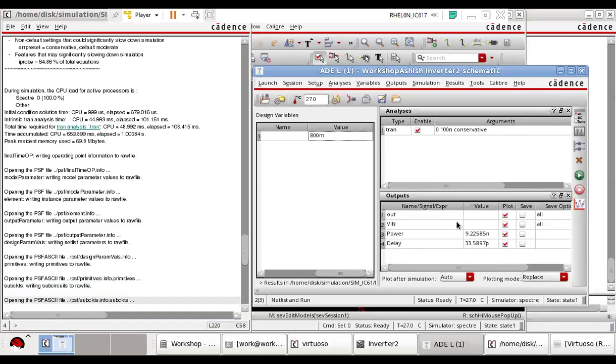We are done with the process corner analysis, where we assumed: what will happen if my NMOS goes slow? What will happen if my PMOS goes slow? What will happen if my PMOS goes slow and NMOS goes fast? Because of environmental conditions, heat, their mobility, concentrations. So if this happens to your IC, what will be the extreme results?